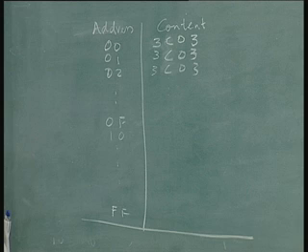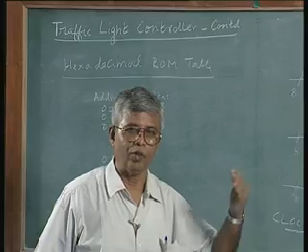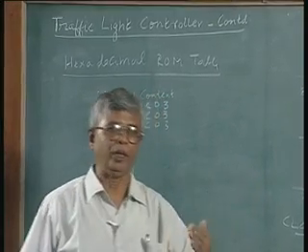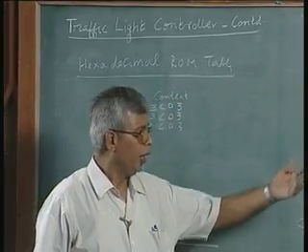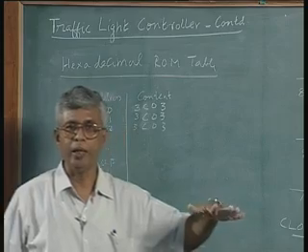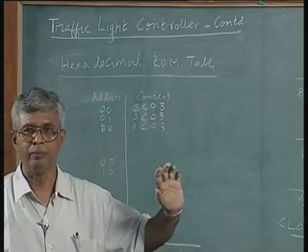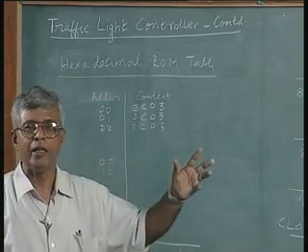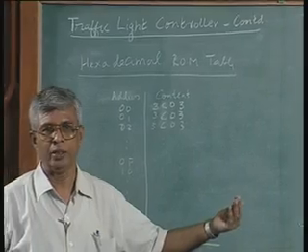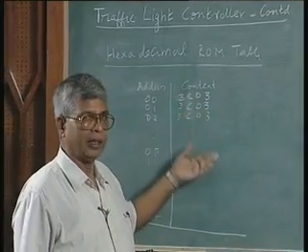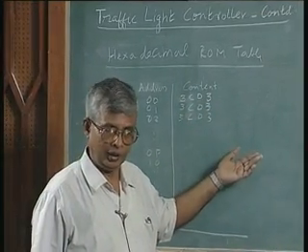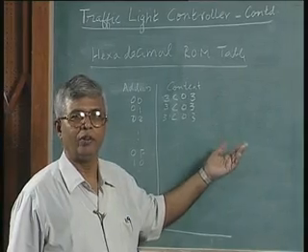And then you can go to the next step and have a programmable array logic. We will not go over all of those again because we have already discussed the difference between PAL approach and the ROM approach. Again, ROM approach, PAL will have a PAL table which is a simplified form of a ROM table because redundant entries where there is no activity will be removed.